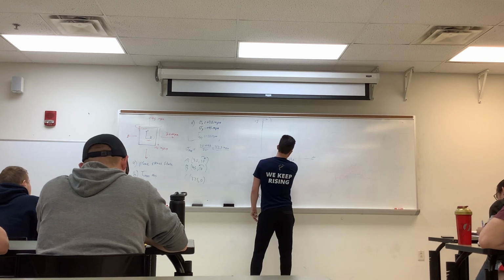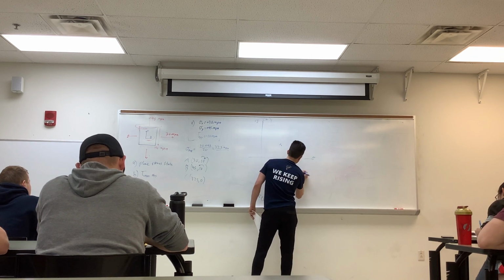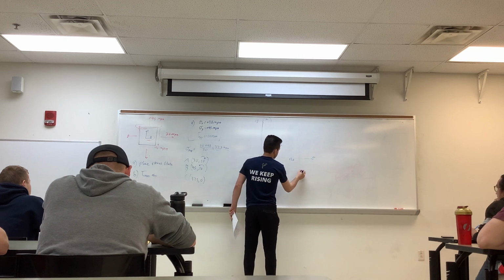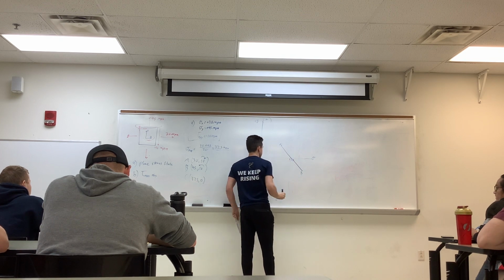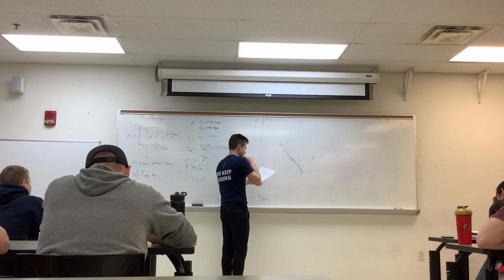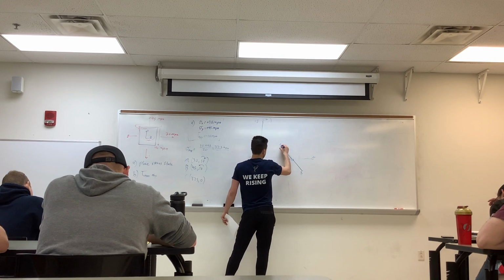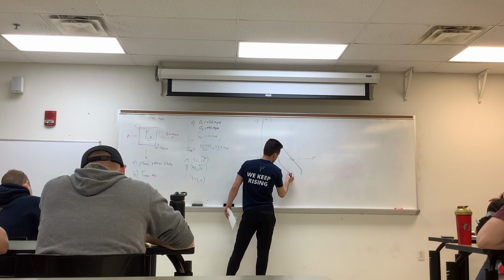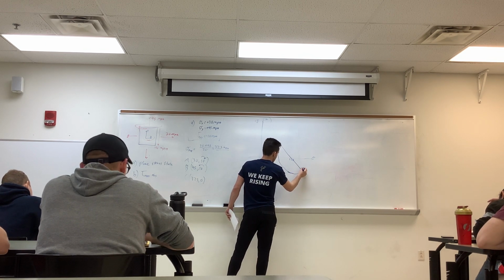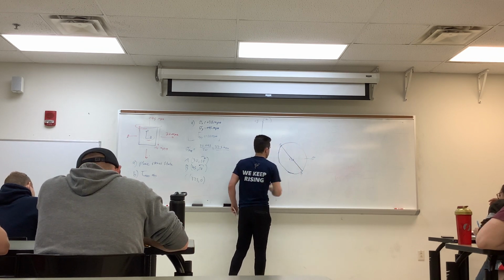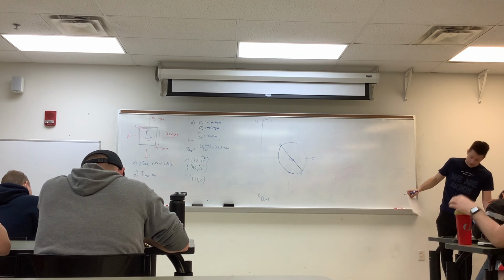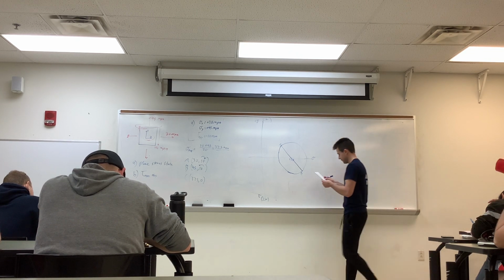And then point B, let's say somewhere down here, which is at 45, 10. Drawing a line between the two, we have our stress state, and then creating the full Mohr circle between everything. I'm not going to grade you on your artistic ability, so try and make it as close to a circle as you can.